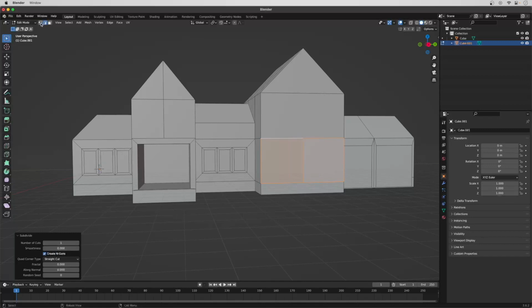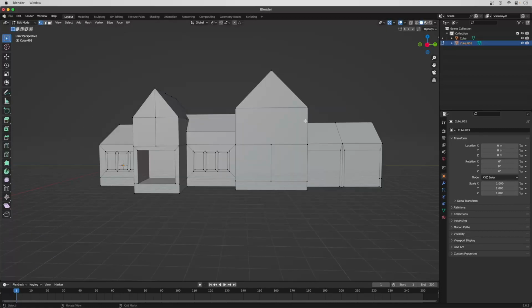And I'm gonna go to Vertex Select. Now I'm gonna go to the snapping tool to make sure it snaps onto the vertices. So turn on this magnet and go to this drop down and go to vertex, not increment. Now I'll go to my knife tool. Select this one. Now it's Z on the Z axis, so click Z. I'll go there and hit the space bar.